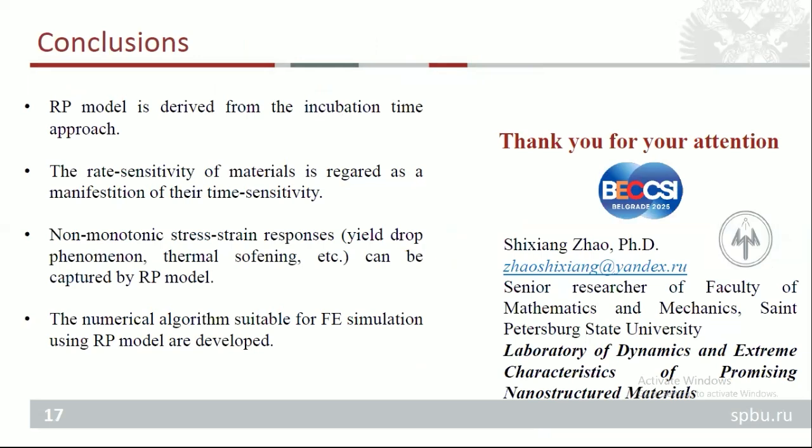That leads us to the conclusion of my presentation. First of all, the relaxation model of plasticity is derived from the incubation time approach, using the relaxation time parameter instead of being introduced empirically. Also, in our approach, the rate sensitivity of materials is regarded as a manifestation of their time sensitivity. The RP model is able to capture different non-monotonic stress strain responses, including the yield drop phenomena and special thermal softening behavior under impact loading. We also developed a numerical program suitable for performing numerical simulation using the RP model. That's all. Thank you for your attention.